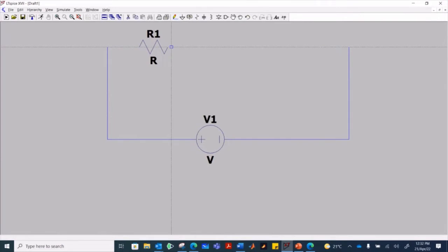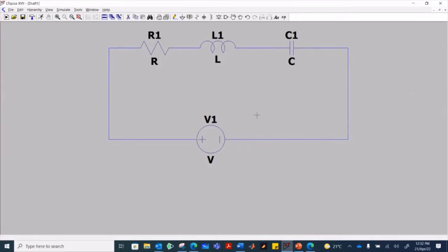Y again, click, and then escape. Then we add the inductor, just shifting that around, click. We click again, the wire, click, and then escape, and then click again, then Control R, and then line up and escape. Then we need to close up this circuit, because obviously the circuit needs to be closed so the current can run through the circuit.